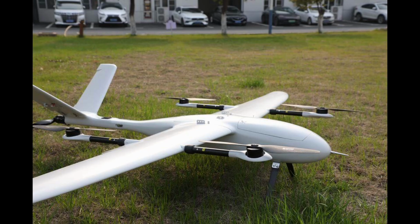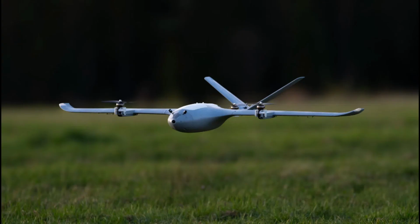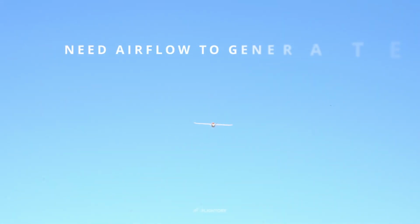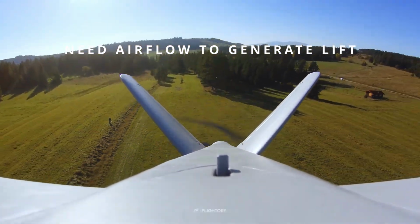Let's start with fixed-wing drones. These are probably what you picture when you think drone that looks like an airplane, because it basically is one. It's got wings, it's got a fuselage, it's got tail surfaces for stability and control. Here's the core mechanic behind it. A fixed-wing drone must have forward motion to stay in the air. You can't just hover. The wings need airflow to generate lift. So there's a motor pushing it forward, the wings generate lift, and boom, it flies.